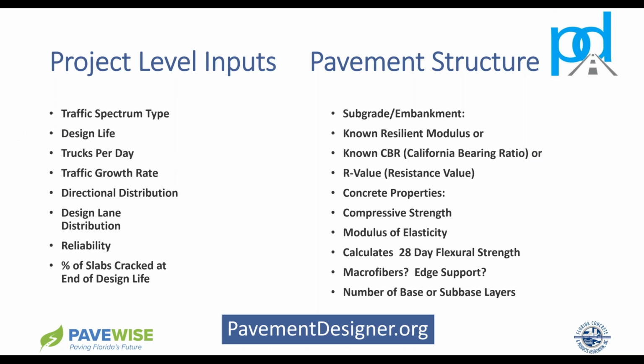Now, I wanted to make you all aware that there are several things that you have to put input for in Pavement Designer, but they're not that difficult. But not all of us have that information. You may have to discuss this with other folks. For example, what is the traffic spectrum? A lot of us pavement designers may not know what that is, but you can probably ask a planner and they can tell you what the traffic spectrum type is. You as a designer, you can pick the design life. The Florida DOT right now, in the latest rigid pavement design manual, was 20 years.